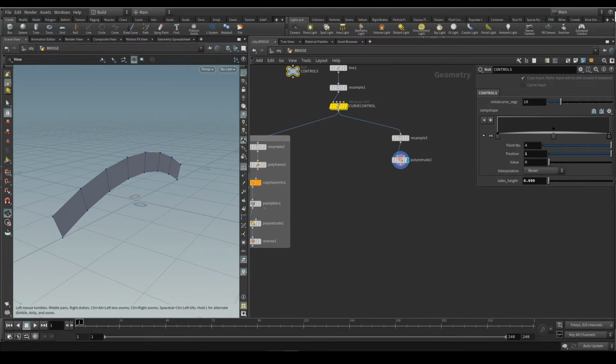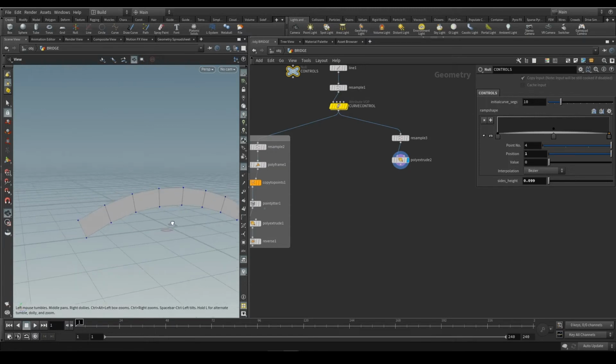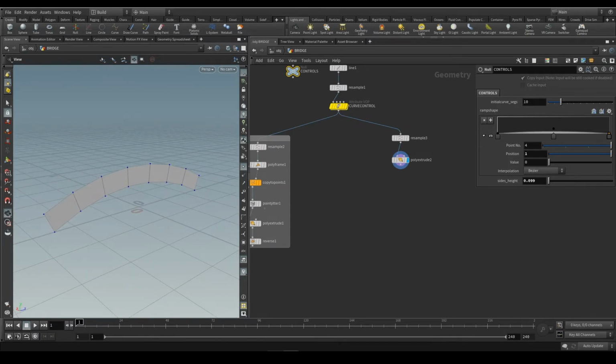Something very interesting right now. I want to give shapes, special shapes, and to give special shapes, I will iterate. I will do a loop on each primitive. There, I have some primitive, the faces. I can display the primitive numbers right there with this button, and I have 6 primitives.